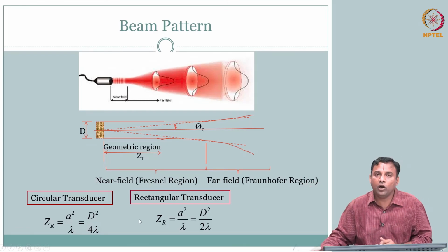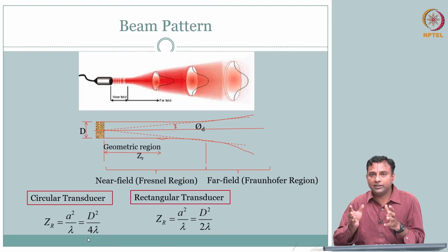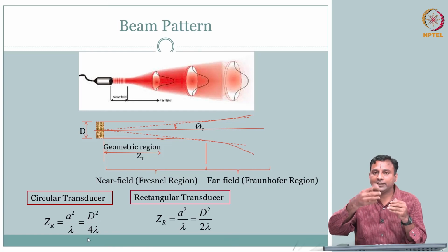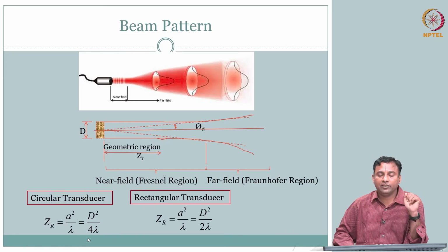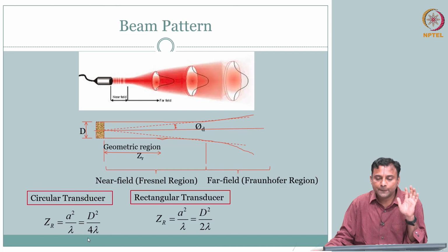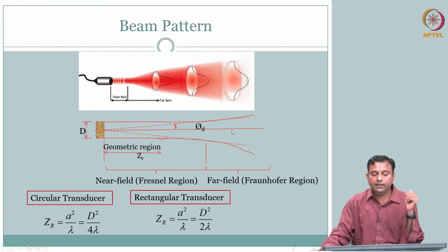So now we will talk about how it spreads out and what happens to the wave when you use this transducer. Then we will come back and say, okay, now I understand how the wave diverges. So what happens if it hits my scatterer, my object, which is a distribution of reflectivity? What is the echo I am getting, and therefore our imaging equation and image reconstruction, that part we will get. Okay, so we will stop here with the beam pattern. We will continue further. We have what is called width. You have one direction along z, which is your direction of depth. We talked about axial resolution.